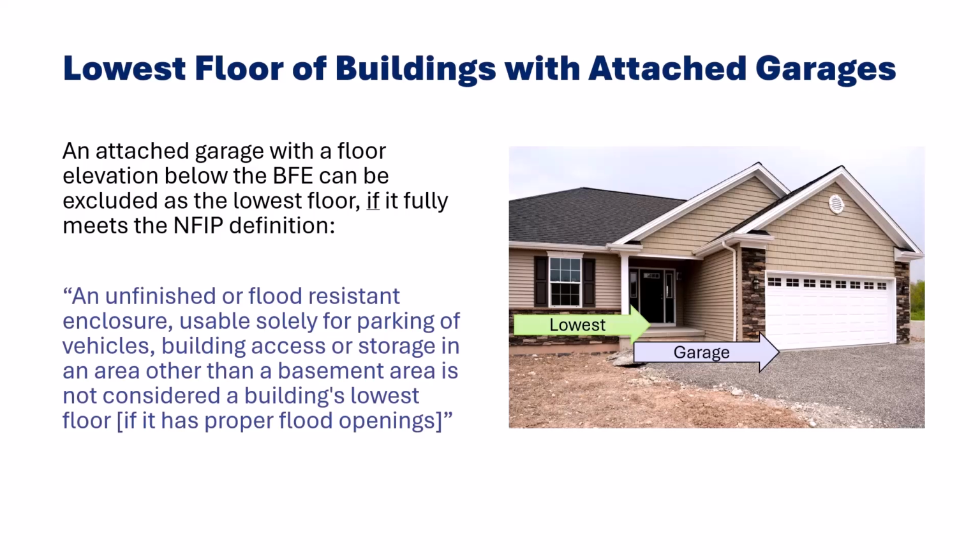An attached garage with a floor elevation below the BFE can be excluded as the building's lowest floor if it fully meets that NFIP definition of an unfinished or flood-resistant enclosure that's usable solely for parking of vehicles, building access, or limited storage in an area that's not a basement, not fully below grade, and has proper flood openings.